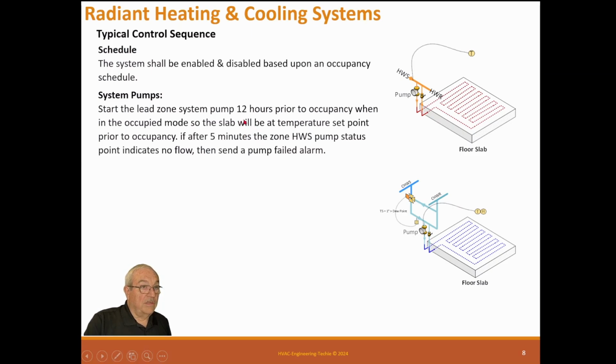So this 12 hours right here can be reset using an optimal start. So if it only takes 2 hours to get to temperature, then you wouldn't want to start at 12 hours, you start at 2 hours.